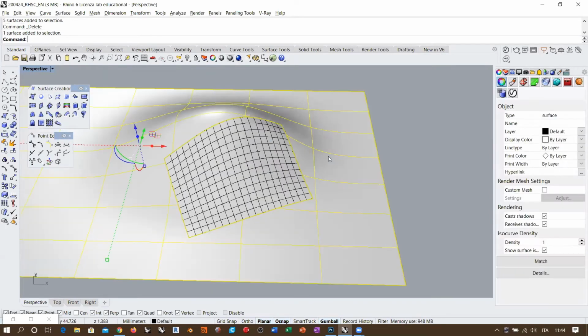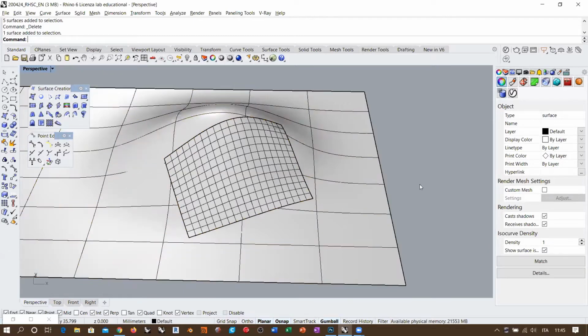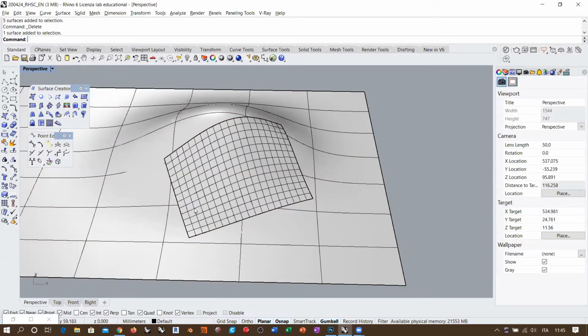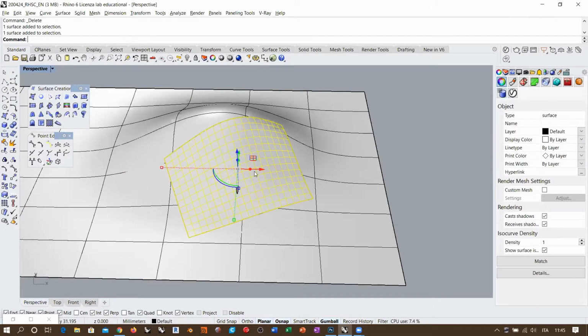In our case, things are particularly regular because we started from a double curvature surface in an internal part which was trimmed, but all the orientations that we get along the edges of this hole are always curvature continuous, okay, because they belong to an internal part of a surface. So what we are doing here is using a network surface to patch this surface, okay?